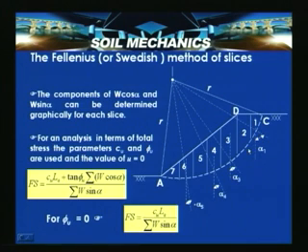So, after having obtained this, when it is marked to a scale, then by drawing the lines to the assumed center of rotation, we can measure alpha 1, alpha 2, alpha 3, alpha 4, alpha 5 with vertical. So, this vertical is nothing but the line of direction of the weight force for a particular slice. So, here alpha 1 is shown, alpha 3 is shown, alpha 4, alpha 5; here observe that it changes sign.